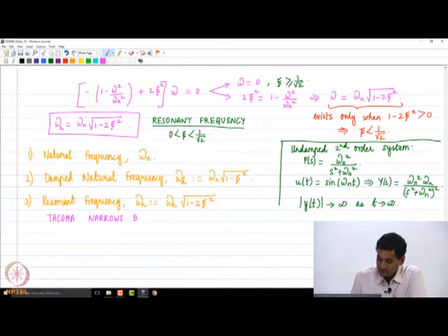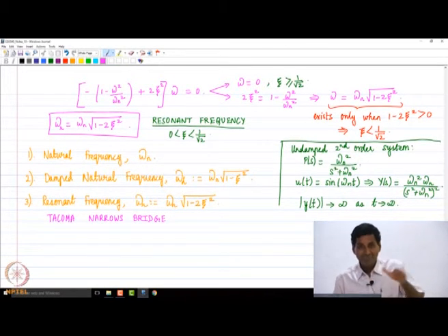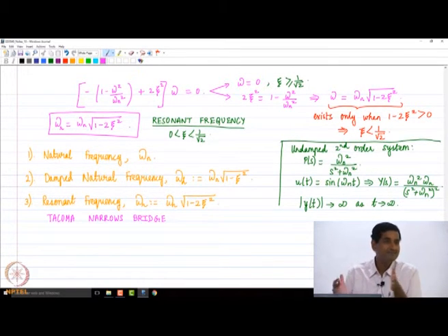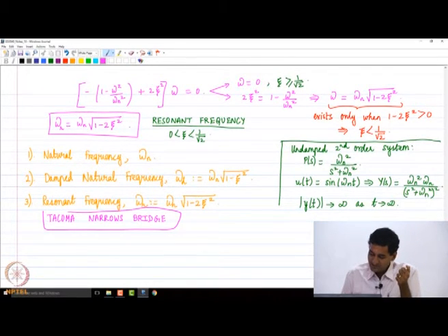You will see that the wind essentially excited the resonant frequency and the entire bridge swayed. Mathematically the amplitude is bounded, but the structure failed because of the excessive oscillations. So just watch the video. That is resonant frequency.